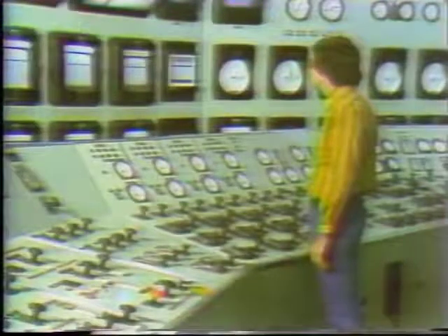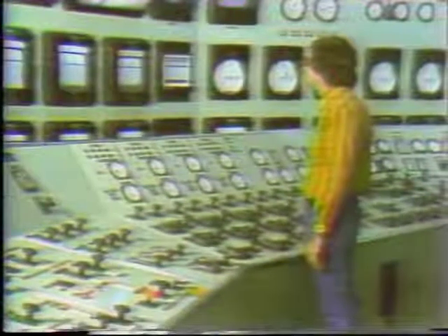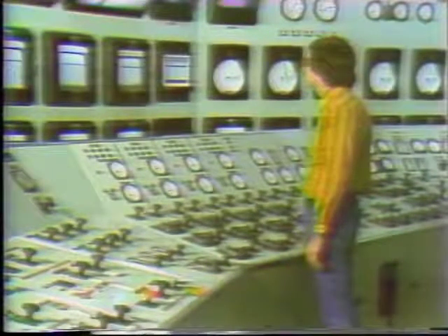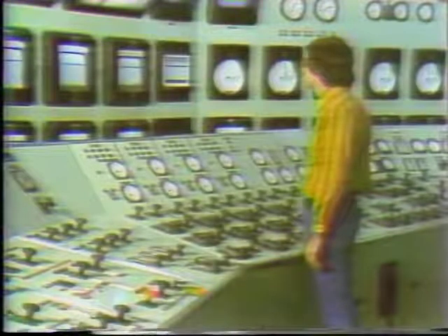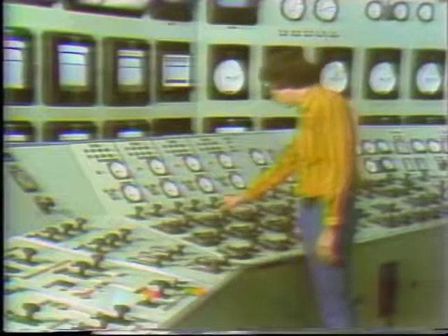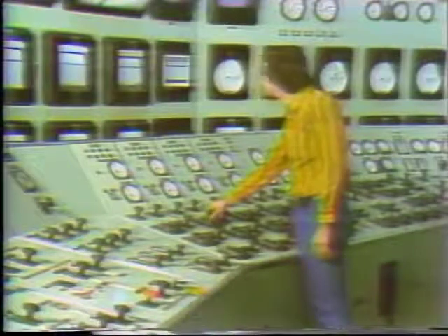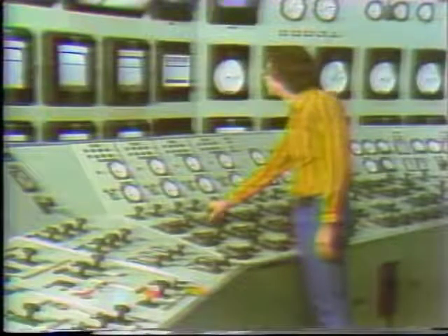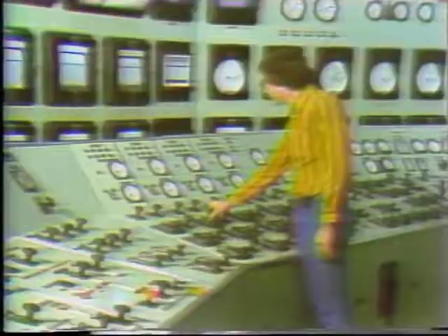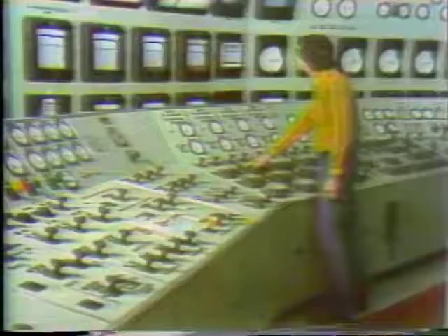Now, while all of this is going on, the operator is making routine checks of the flow rates and comparing them to what he has seen under the same conditions before. Should he spot what he considers a potential problem, for example, the combustion air flow rate may be too low, he may have to make adjustments to an automatic control system. In most cases, this will restore the unit to normal operating conditions.